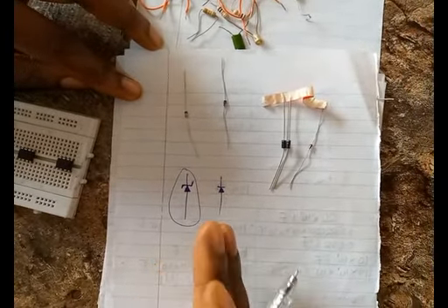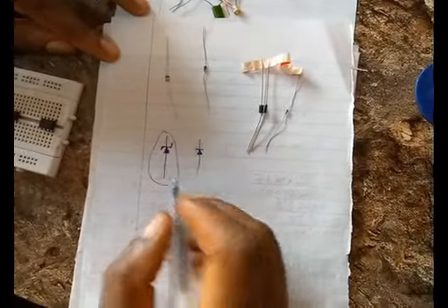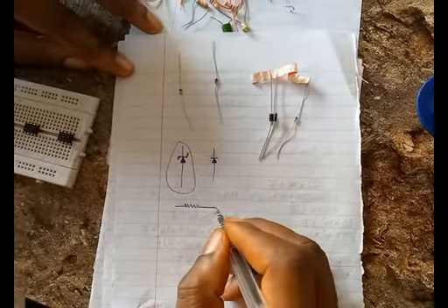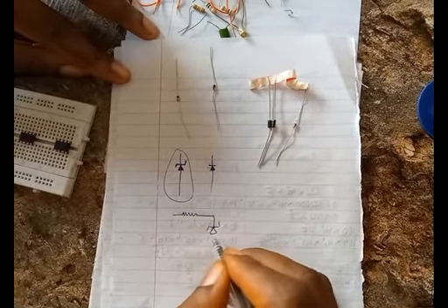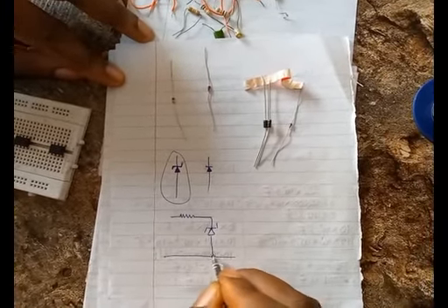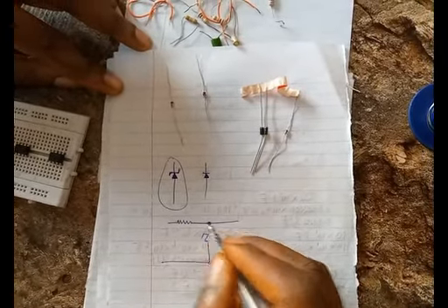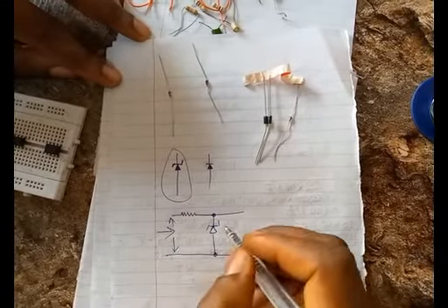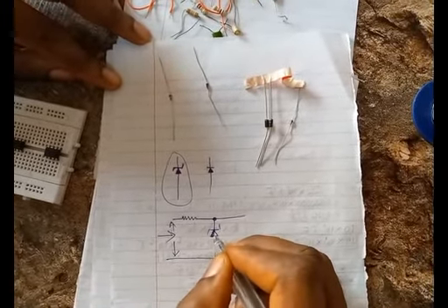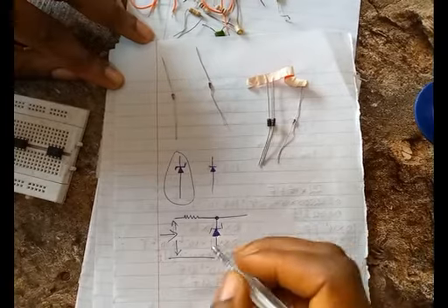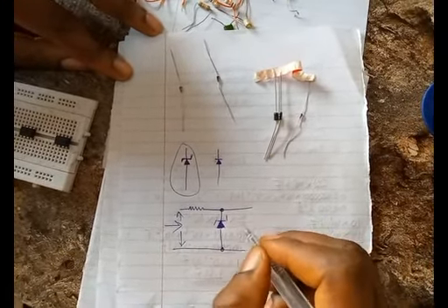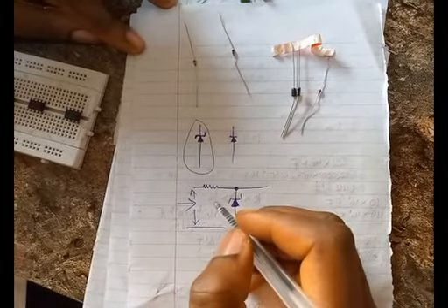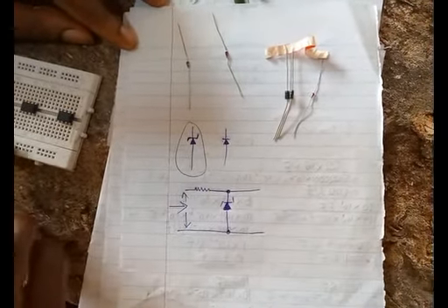But like I said, we're looking at this, so let's just see. One way you arrange this in a circuit is simply adding a resistor this way and then something like this. If you arrange it this way, a particular voltage enters at this point, and then depending on the Zener voltage, you have a particular voltage coming out regardless of what's happening to the voltage here. I'm going to show you that in a bit on my breadboard.